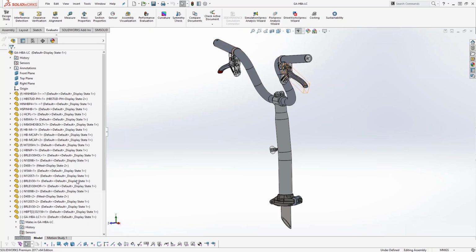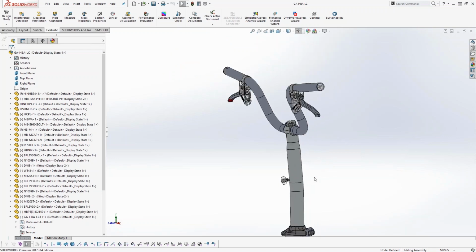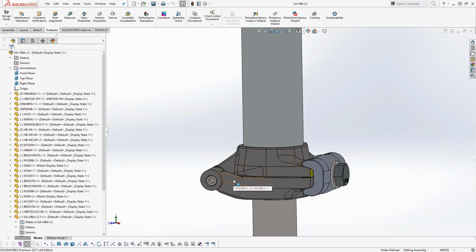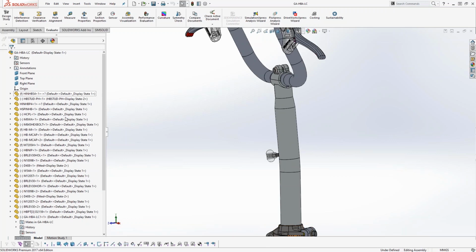handlebar assembly. So there's about 30 or so components in here, from the handlebar, brake lever assembly. We've got a bolt in place here, which clamps the handlebar support to the handlebar. Hinges to the handlebar support and to the steerer pin. Fairly untidy geometry, plenty of surfaces. What I've done, I've also flattened the structure just really for simplicity.